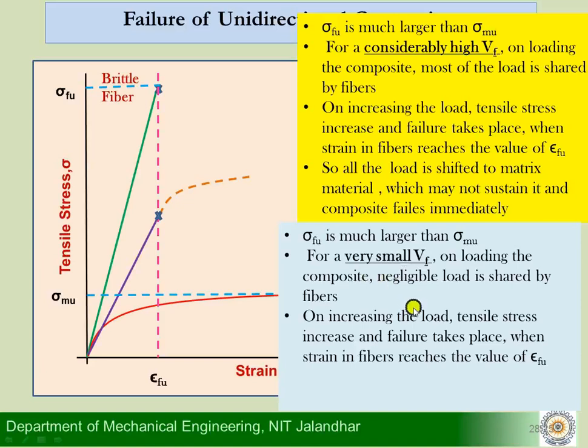So when the amount of fibers is very, very small, obviously the load taken by the fiber is also less. So negligible load is shared by the fibers. Most of the load is taken by the matrix itself. So then what happens when you increase the load?